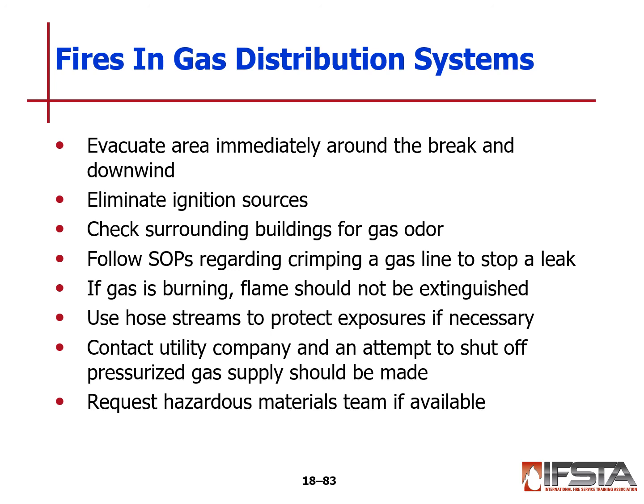We want to evacuate the area immediately around the break and downwind and eliminate all ignition sources. So running vehicles, smoking, anything that would be an ignition source. Check surrounding buildings for any odors of gas.